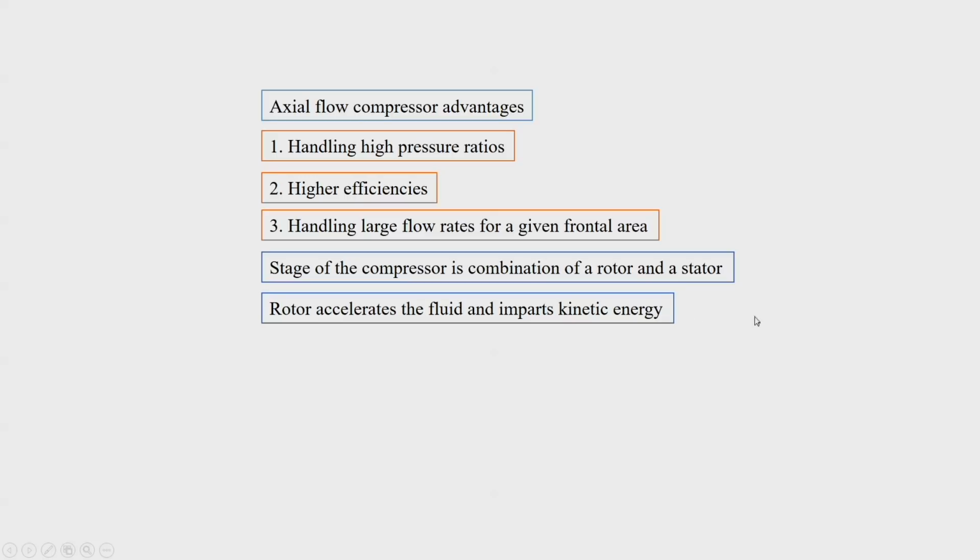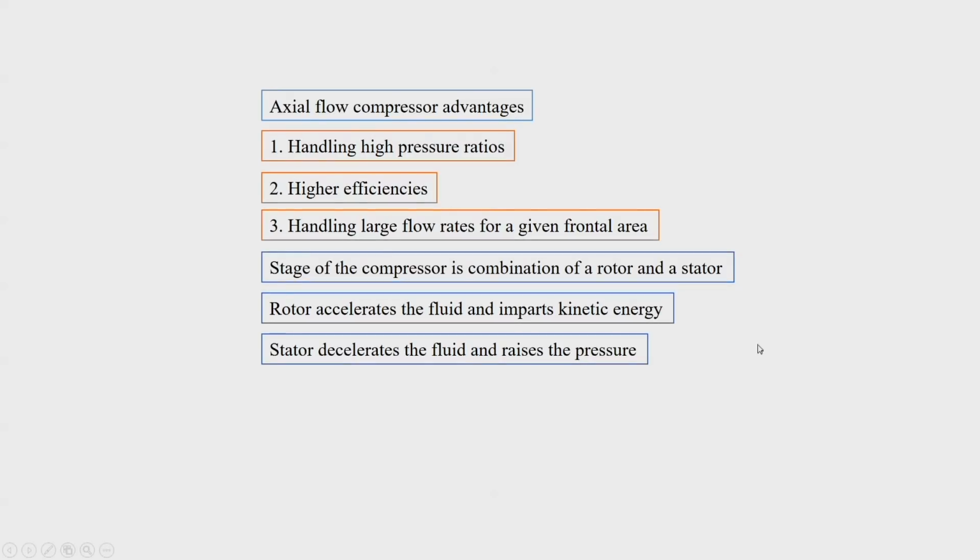In this case, the rotor accelerates the fluid and increases its kinetic energy. In the simplest case, this is the job of a rotor. The rotor is supposed to put kinetic energy into the fluid and increase its energy content. It is the energy-adding component of the compressor, and it also partially helps to raise the pressure, but not completely. But then there is a stator, which decelerates the flow and raises its pressure completely, to the required value after that stage.